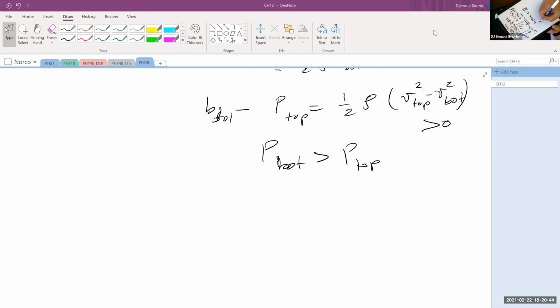And the rate with which it's changing, namely V1, that is the velocity with which it's moving down. So V1 is equal to dH over dt. Remember, V1 and V2 are related by that expression, namely A1 times V1, which is dH over dt, by the way, is equal to A2 times V2. And V2, we found it from the previous expression. It's going to still hold true.